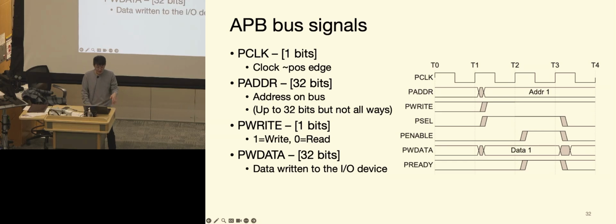And yeah, some of the bus signals, when we draw them out. The APB uses a small set of signals for communicating between the bus masters and the peripheral slaves. For example, the PCLK or peripheral clock is an input to the slave device, and the clock signal is for synchronizing the communications across different peripherals and to the core as well.